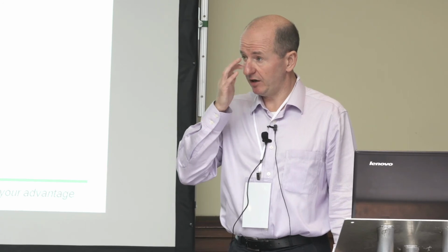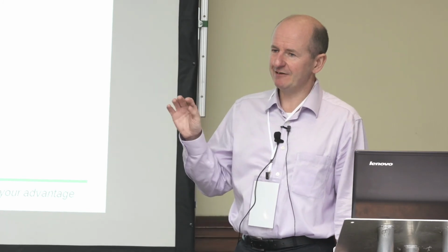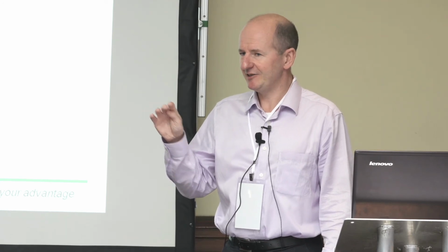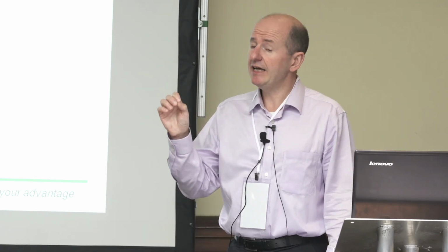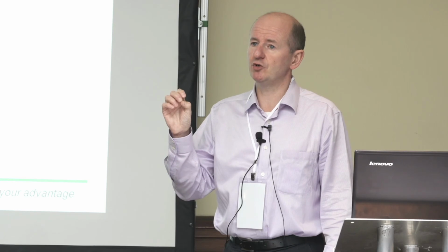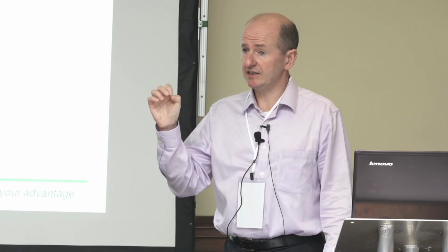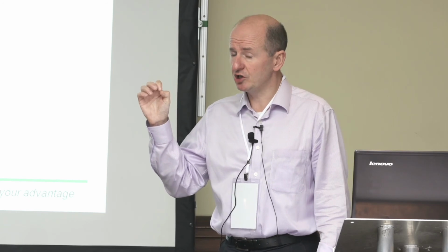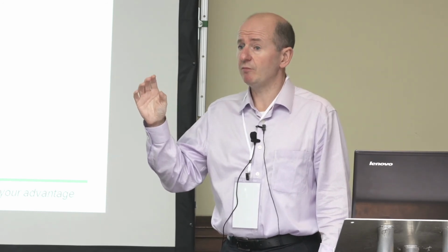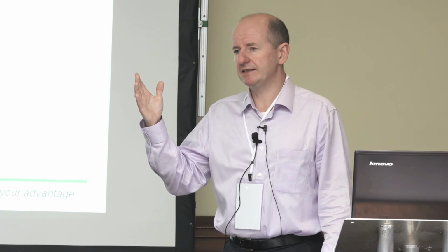You mentioned that gate current was a potential issue with your layout. It's not huge, to be honest, but as you drive it into compression, you do get more. It varies from process to process, and different foundries specify different amounts of gate current and then change it again when they get onto the release of a new process. And in honesty, if you've got a mature GaN process that is well designed, it's not hugely higher than a GaAs process. But when you're driving it hard, you might see maybe even as much as a milliamp per millimeter.